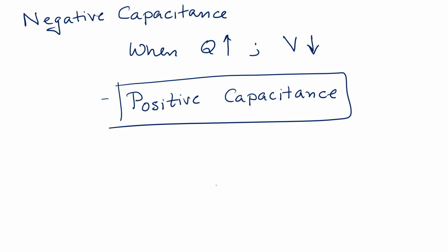Three things you should keep in mind. Capacitance would only depend upon the geometrical properties of the conductors and the dielectric material in the middle. Capacitance exists even when you have not put any charge on the conductors. And as we will discuss, capacitance would always be positive. Alright, next we will see how we can calculate capacitance for any arbitrary shapes.